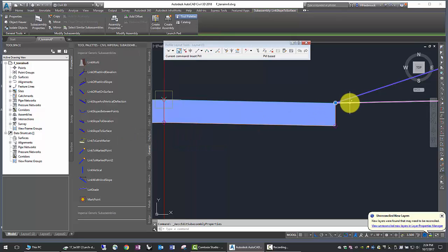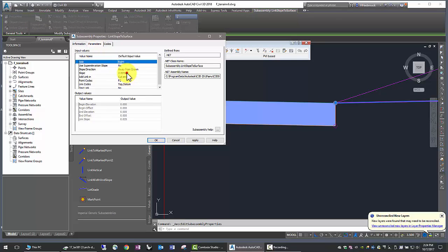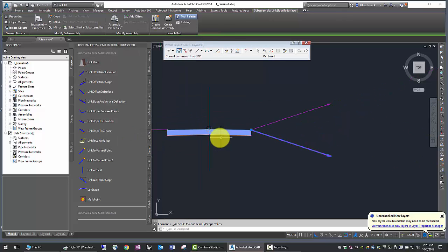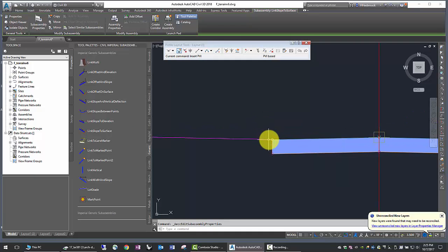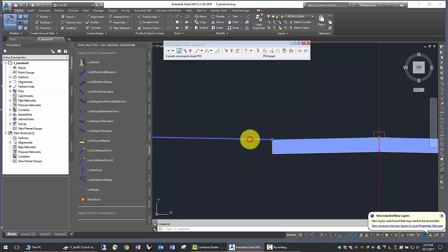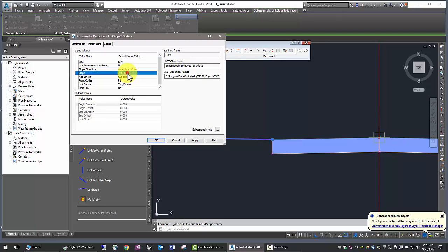And we're going to have that in a positive condition if it is below the ground, so in a cut. And now we're going to edit it again. And here, breaking convention, negative 33%, so that in a fill condition, it will also seek a solution. If we only do it in one, it'll only seek to do it in that one resolution.